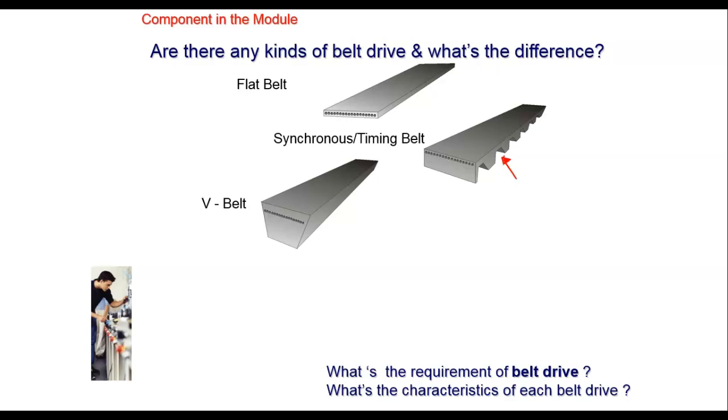So sometimes you'll see a V-belt that has teeth on it, and those are in there just to make the belt run cooler, and it makes it more flexible. So this is a notched belt. So one of the advantages of these, of course, is they're more flexible, and then of course they run cooler.